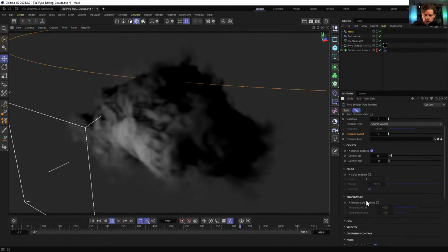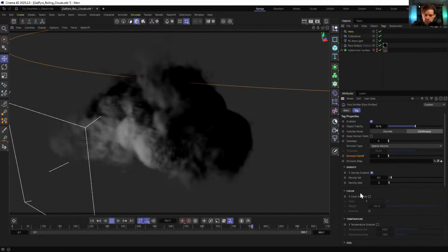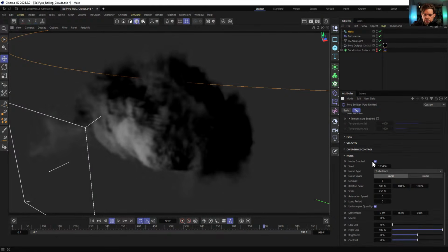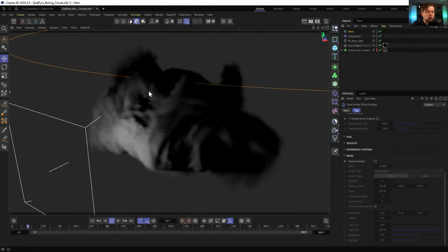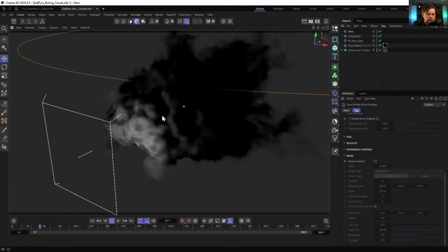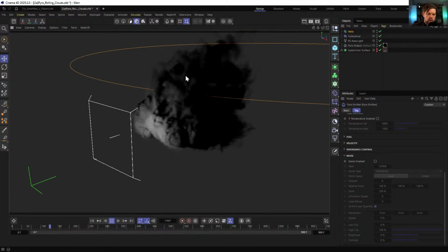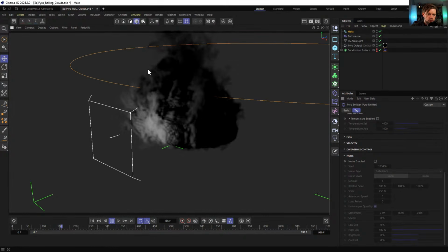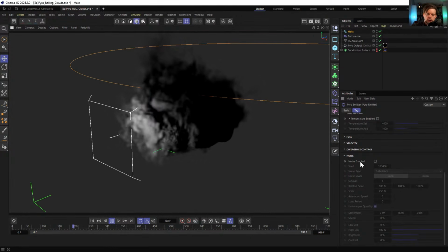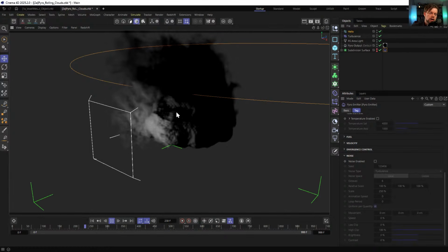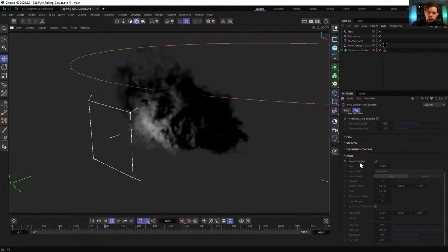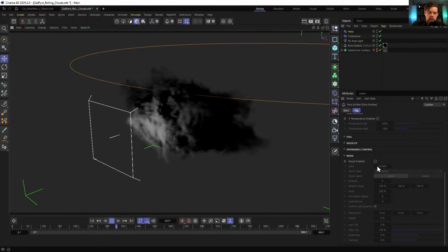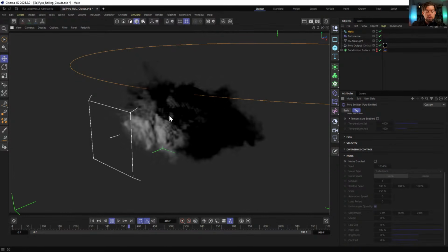We've got these noises. That's fine, but that's not helping specifically. Also, keep in mind, sometimes you might want to turn off the noise. If I turn off this noise, there's just going to be full density everywhere. And actually, yeah, you see immediately that all this stuff feels denser and there's just more cloud to drift around. And that's because essentially Pyro is trying to make a big cloud of density, and this noise is erasing out certain areas of it. So by turning off the noise, we're saying, well, you've now made more density.